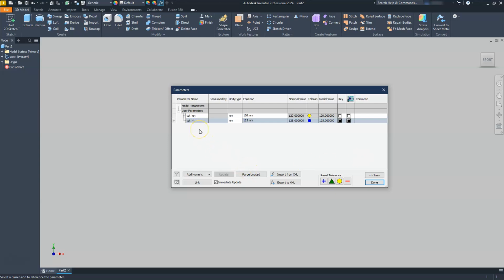All right. If I want to, I can add a couple of those in here as well. Well, not really arrays, diameters. So if I go to the add numeric, and I'm trying to give a good name for it, let's call it a small radius. So small rad. And that's going to be 20, right? So that's going to be my small radius, and I think I only have one major dimension on this drawing. So I'll go back to add numerical, just call it DIA, and my diameter here, and that's for all of these little circles. Let's call it 15.